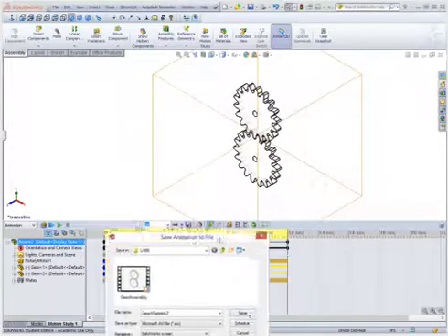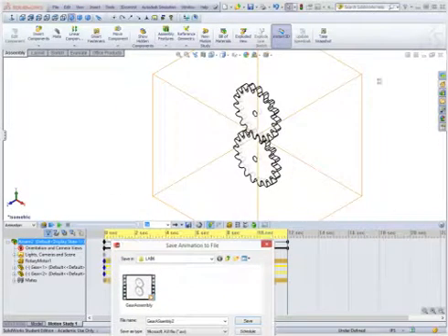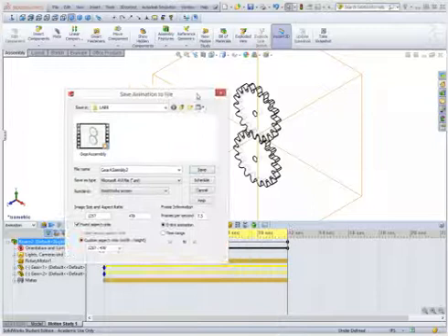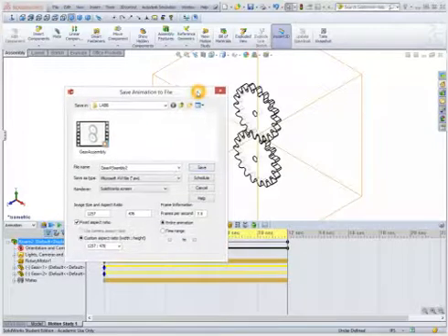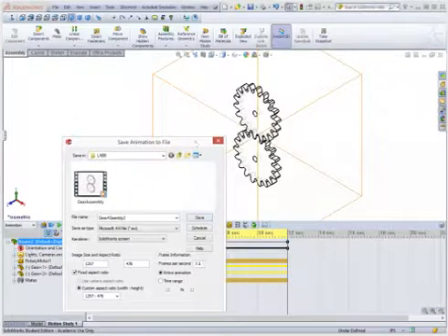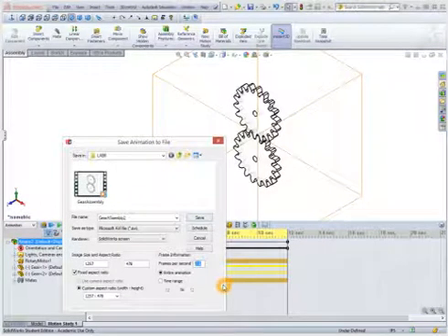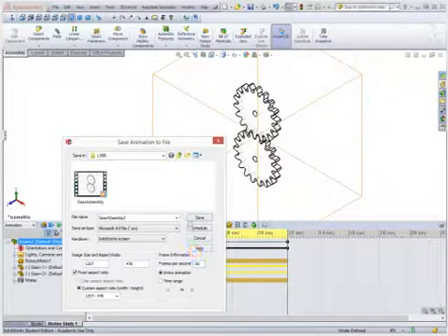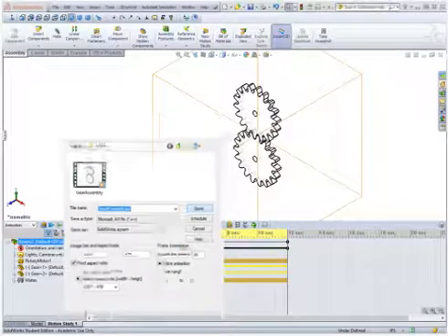So this is one of the downsides, is it's going to pick this area right here and use that for our actual animation. So if you want to condense that, you have to kind of reshape the window in SolidWorks. Of course, you can go back and edit it later, but if you have a full screen on a large monitor, you're going to generate a pretty big video file. This frame rate's probably a little bit too slow. I'd say 15 or 30 is reasonable, so let's just go ahead and choose 30 just to see what it looks like. We're going to save this now.